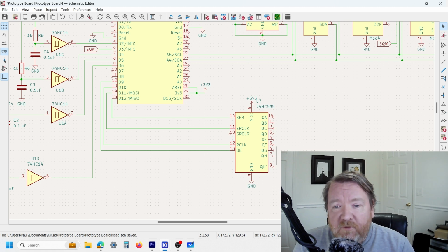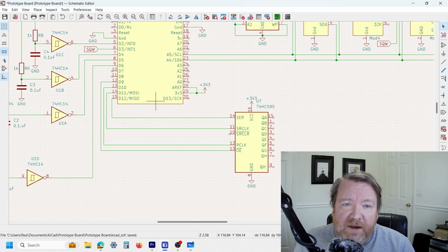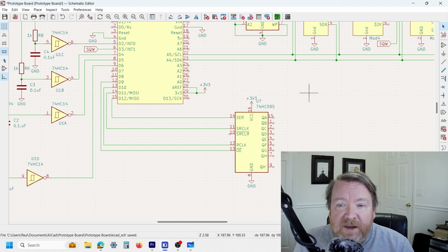Or you could use this approach where all of the segments you want to be enabled will be enabled all of the time. And if you then want the microprocessor to be doing other tasks, it can be doing other tasks and the LED display will be fixed by the shift register. So it enables effectively outsourcing some of the data output tasks to an external chip.